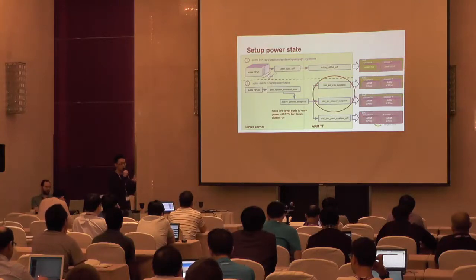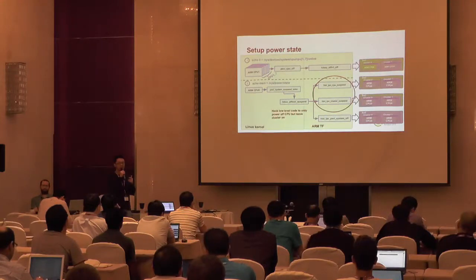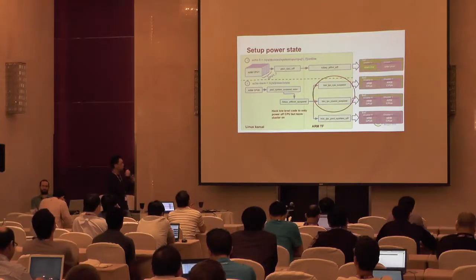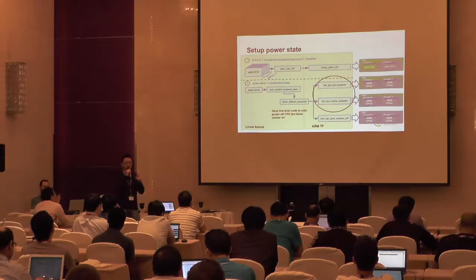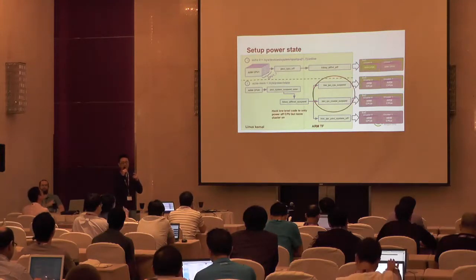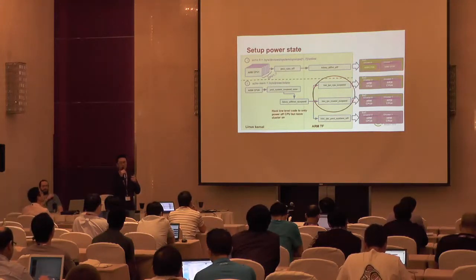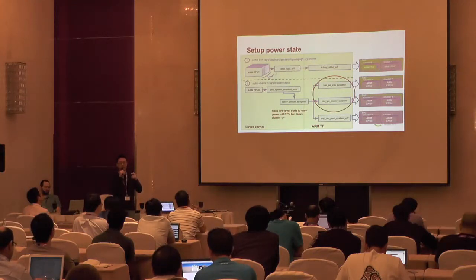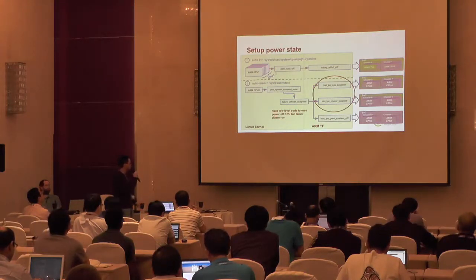For CPU 0's low power state, we can hack the trusted firmware, so we can select the specific hardware idle state. For example, we can hack the flow to let the CPU just run into the power off state, or let the cluster be powered off, or let the system run into the real suspended state. In this way, we can get different power data for different idle states. So this is the method.